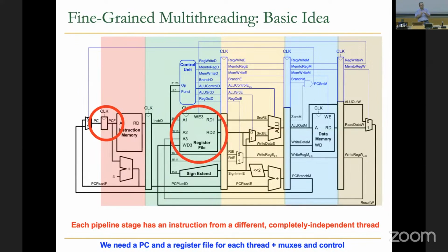But in the paradigm of fine-grained multi-threading and also GPUs, because you want to quickly switch between warps, you need to keep the context on chip, such that it's just changing some control registers or multiplexers. I was running warp 0, now I just want to run warp 1. And the registers of warp 1 are ready. I just need to load them from the register file. And essentially, you don't really need to do context switching.